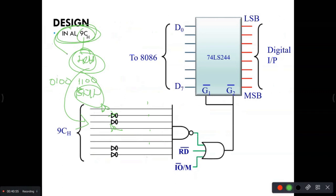Your circuit will be similar. Instead of the write signal, you will have the read signal, because now data is coming inside from an IO device to the 8086 microprocessor. This is the way your 8086 microprocessor interacts with the IO device. Just out and in instruction.